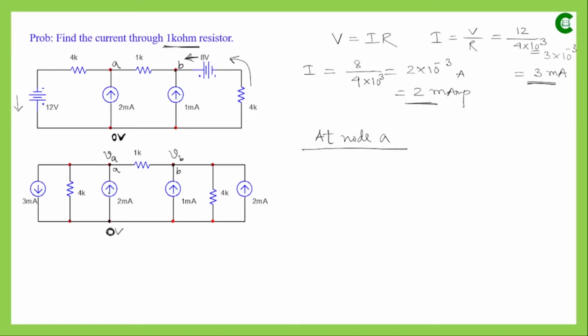It is incoming current, and with respect to this node, this current source is outgoing current. For the rest of the two branches where we have resistors, we don't know the direction of the current. So we will assume as if the currents are leaving that node. If we assume that the currents are leaving, then accordingly we will form the node equation.